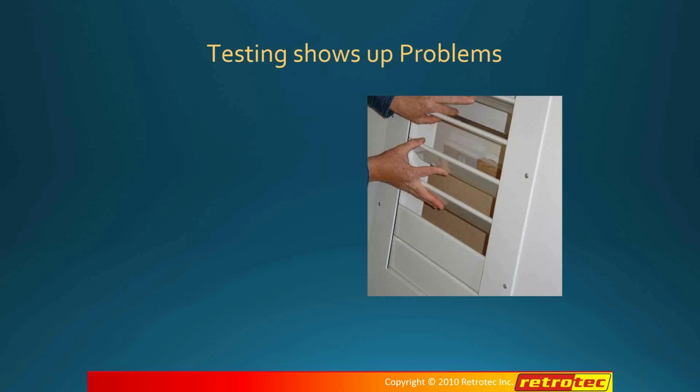So they said to me, Colin, what we do now is we turn on our door fan, we see the vent open, and we feel okay about it. So based on that experience, and the experience of many, many others, I thought, well, what we really need to do is to have a pressure vent testing scenario that allows us to not only install a vent when we need it, but to turn on our door fan and see, first of all, will the vent open at all? And if it does open, how much free venting does it actually give us?